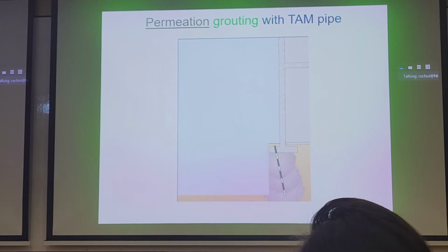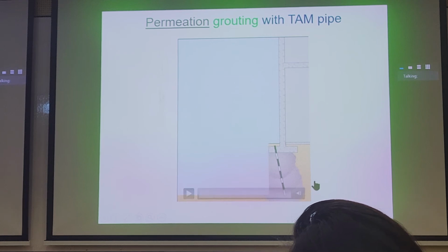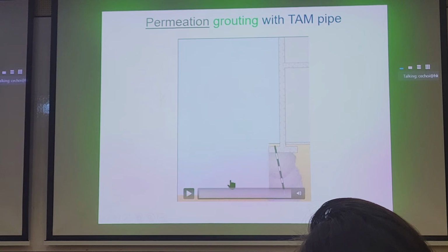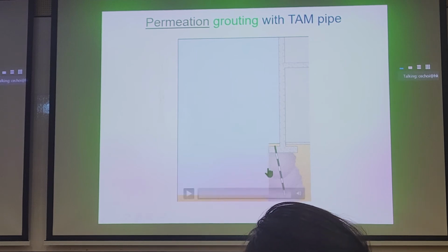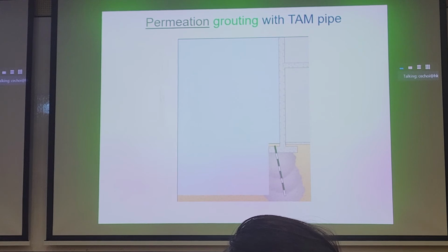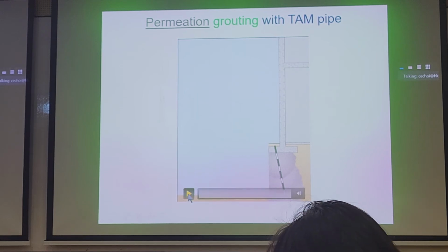So, moreover, what they do afterwards is they can use the grout to do two things. Notice that the grout is underpinning the footing. If you don't underpin the footing and you carry out excavation, what's going to happen? Well, then your building will move into your excavation, right? And interestingly, this grout can also be trimmed off, excavated to be used as a retaining wall. So these are some uses of grout in the field. Let's take a look at the video again.